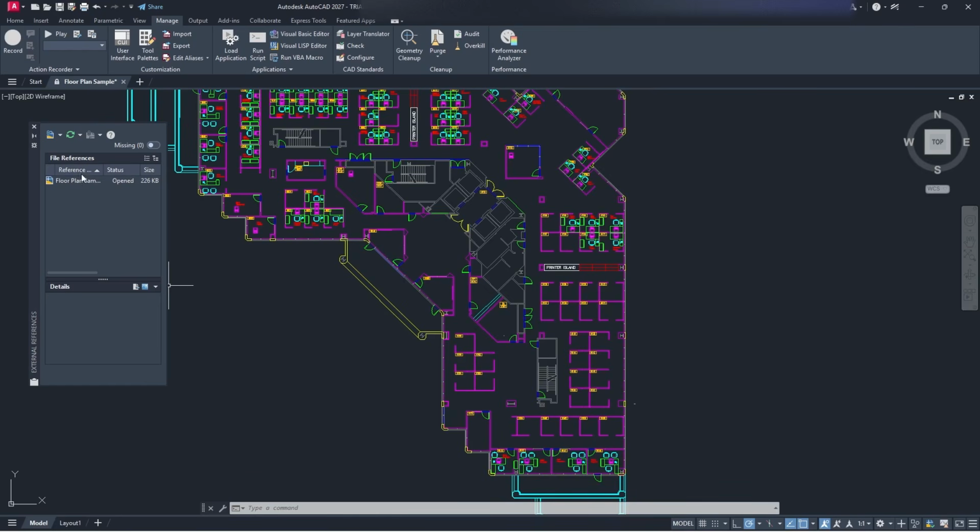So from the missing references view, once you click that, you can then perform the following tasks on the missing references. You can detach the references that you just don't need anymore once you select this, of course. You can update the paths of references by browsing and specifying a new path. So if you moved a file to a different location, you can go and find the new file location without having an issue with that. And then you can also resolve the paths of references based on suggested paths. It's only going to apply to drawings open from Autodesk project only.